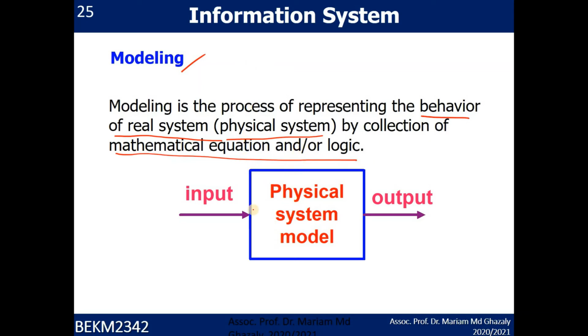So you have a physical model here. After you have modeled this, you can run the simulation in Simulink by giving an input to the system. Input here means that you give a voltage, and then you can look at what the output is. Output can be in terms of speed, temperature, displacement.